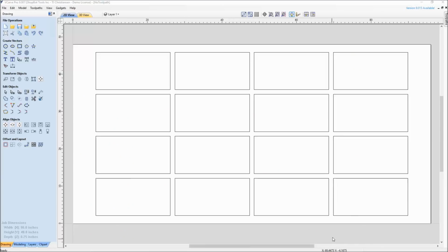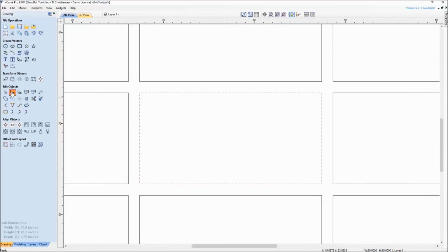Let's start the first one here in the CAD software, and what we're actually going to be looking at is the start point of the cut. You can see a series of rectangles here on this file, and when you're just in your regular selection mode, it's just a selected highlighted pink vector. Well, if you look into node editing, it actually shows you a green square. That's the actual start point of where the cut is.